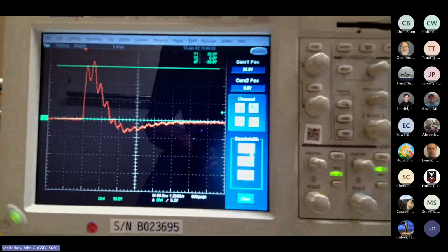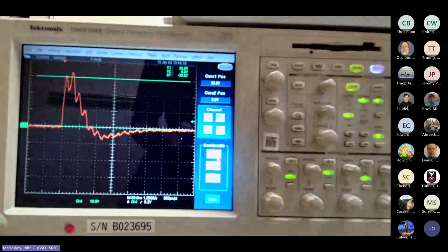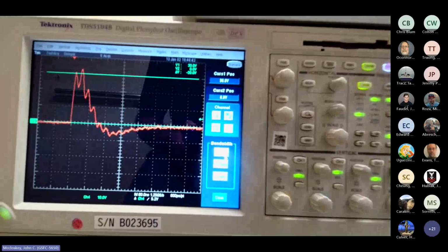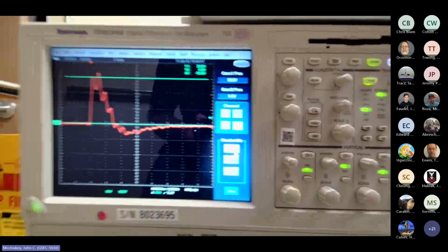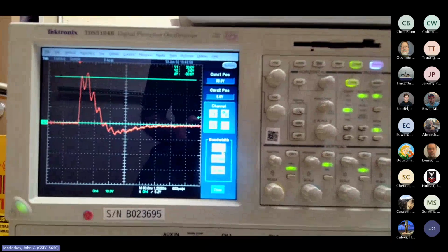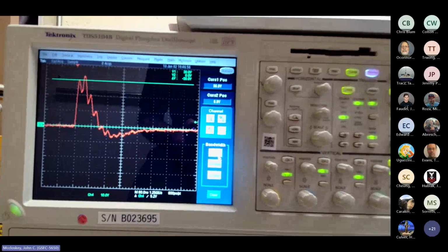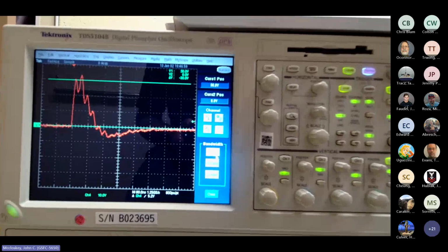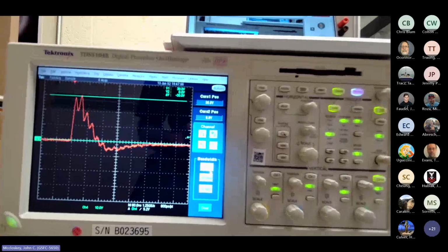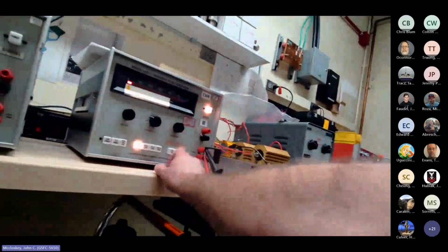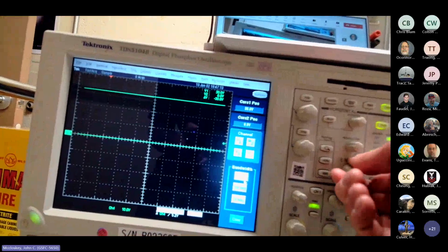Yeah. I mean, this is such a short pulse that any filter capacitors you have in there to deal with CS101 should probably snub out a short pulse like this with no problem. But here we are. If there's a specific requirement or desire to do this, then we should at least be prepared to do it. So, generally speaking, I'll walk through what we generally do for the 10 microsecond pulse, and then we'll come back to this. So go back to 10 microseconds, and I'm just going to leave it as the negative going pulse.